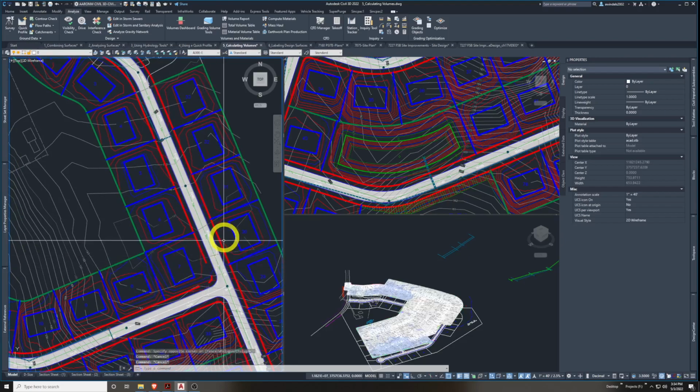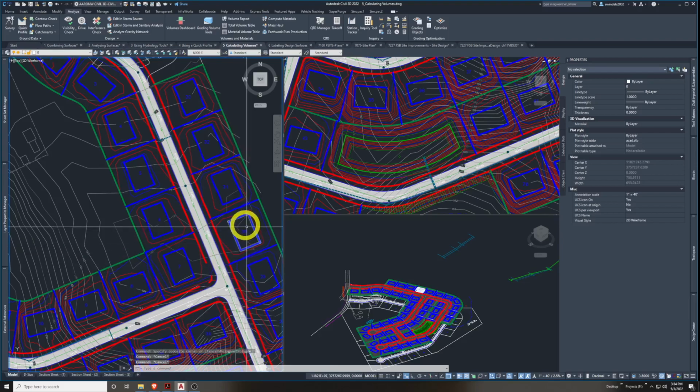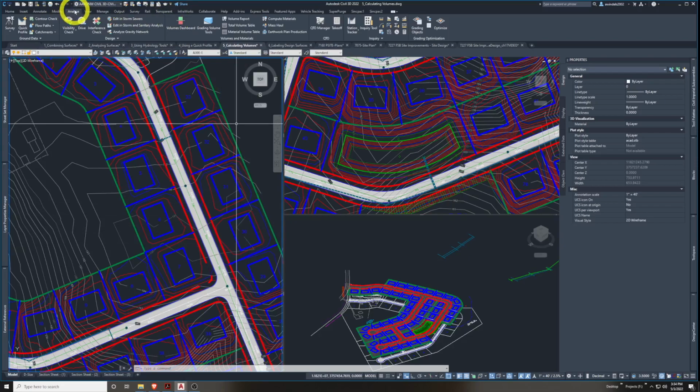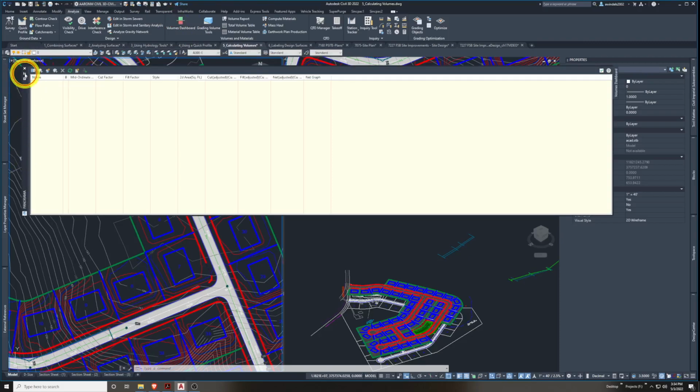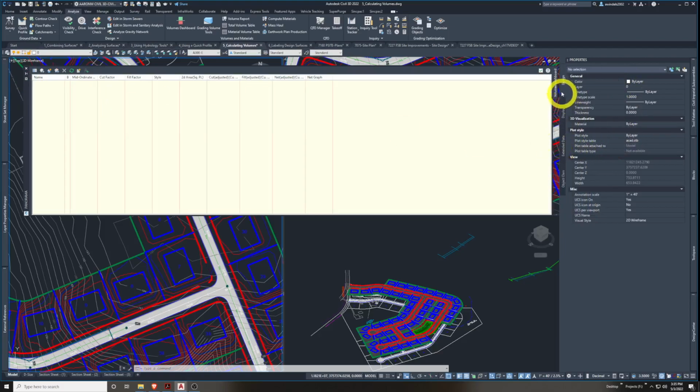So beginning on the Analyze Earthwork area, let's go into this drawing, and we'll start with the Analyze tab. And we're going to click Volumes Dashboard. So we're going to get a panorama that comes up with this. Mine's a little hidden, so I'm going to stick it here, more permanent. And it should be over here on this tab. I'm going to slide it over a little bit so we can see it better. Volumes Dashboard. We're going to create a new volume surface this way.